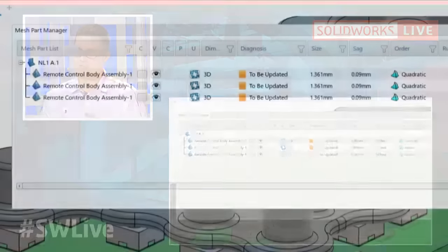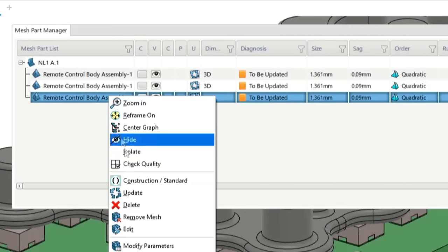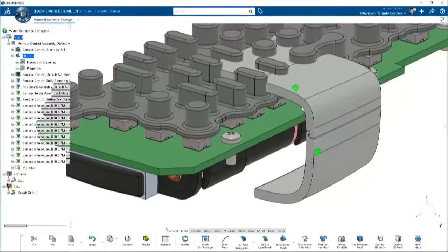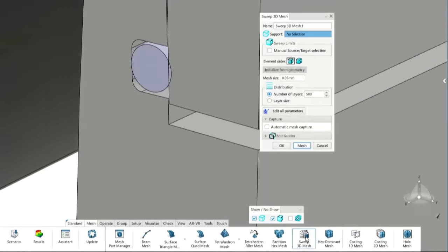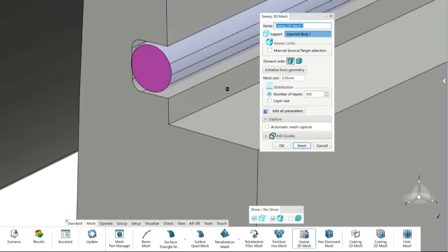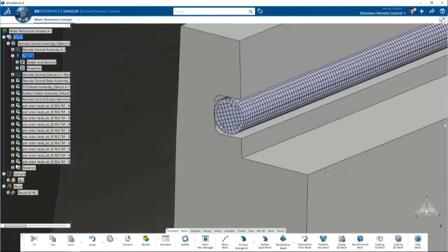While I do have a default mesh set up for each of these, the last one is for the O-ring. And for this type of nonlinear material, it's going to behave differently than the plastic components. I'm going to use a brick element, and I can actually just pick it. It recognizes the faces to sweep it through. So I specify my size requirements, and I get a nice mesh purpose-built for this rubber material.